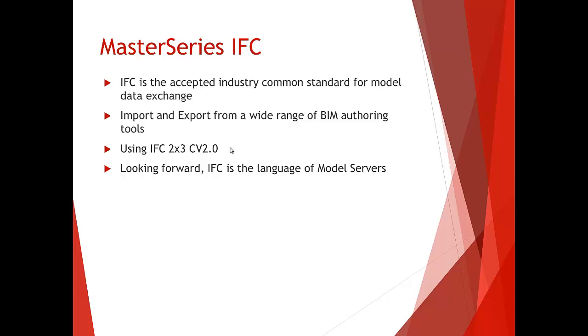But looking forward, what we have at the minute is the ability to both export to IFC and import from IFC. So you can get your models from MasterSeries in an IFC format, or you can import an IFC file and generate a MasterSeries model from it. We'll show you both of those. Naturally, the other question is, what about round-trip integration?